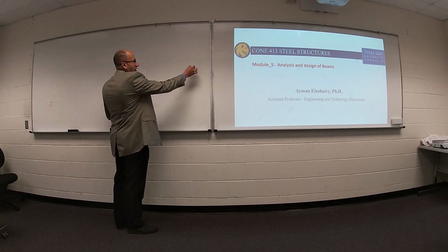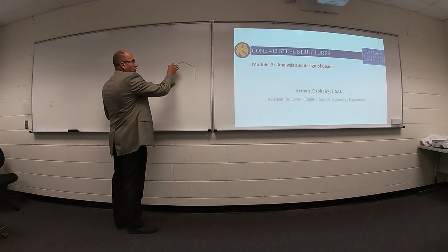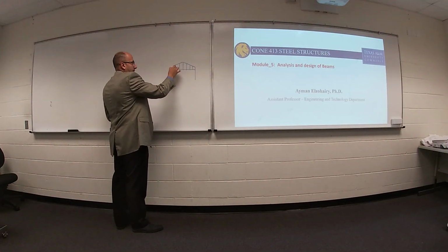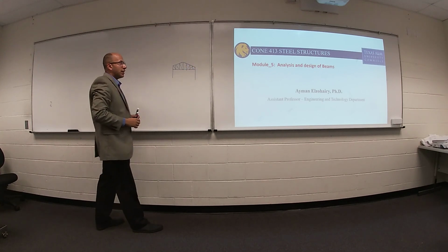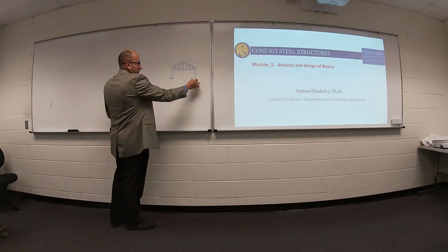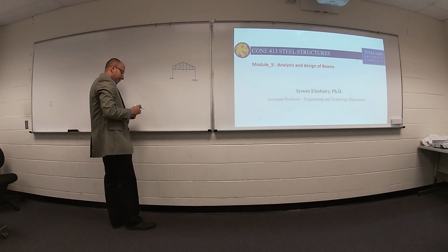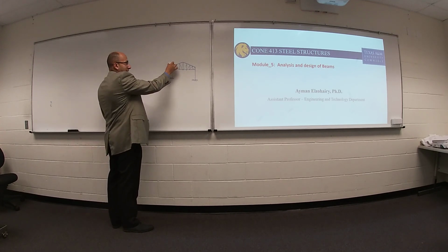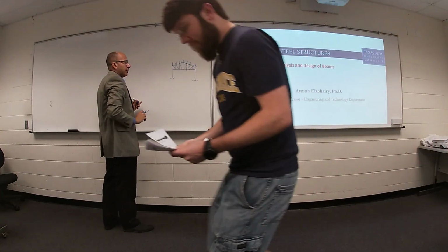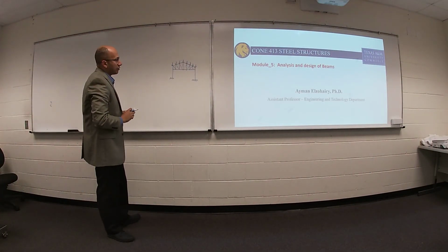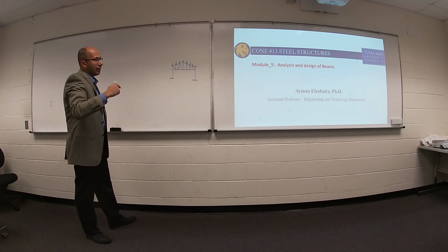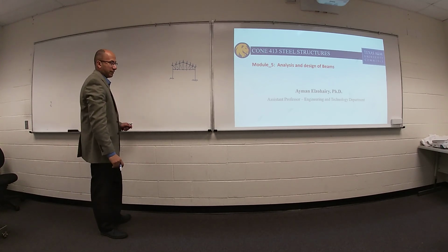We started with how to draw the main system. And we learned a lot about truss. After you draw your main system, we learned also how to calculate your dead load, your live load, your wind load. Using RISA 2D, we are able to determine what is the tensile or compressive force in each member.